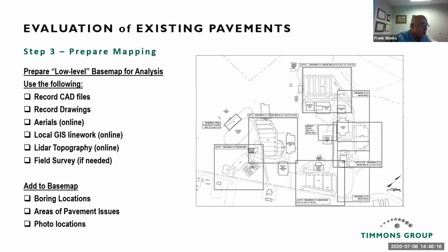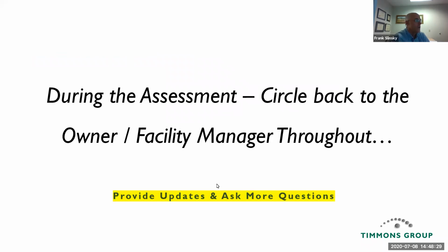Add to the base map any boring locations, areas of pavement issues, some of those measurements you took, and then the photo locations. And during the assessment, circle back to the owner and facility manager throughout. It's important to coordinate, provide updates, and ask more questions.